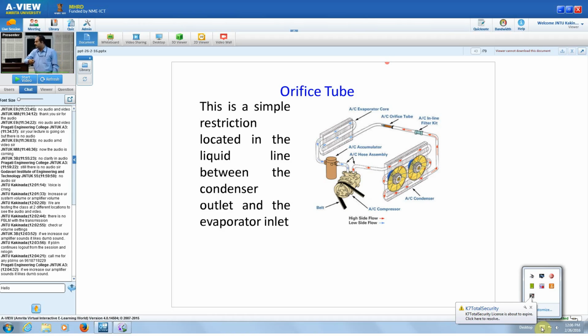Our refrigerator is also the same. We are cooling the products in the evaporator. The total cabin is called the evaporator. Same thing, but clearly there is the compressor, condenser, the expansion device, and then the evaporator. And these are the additional equipment like accumulator, dryer, all this. Next.